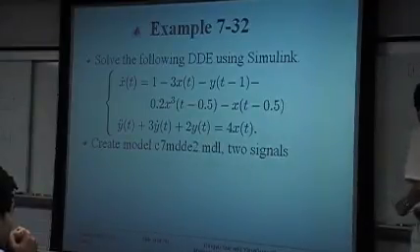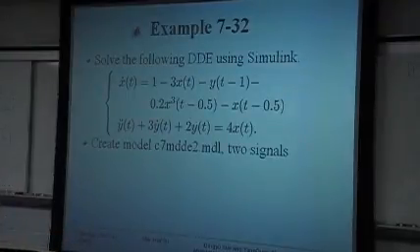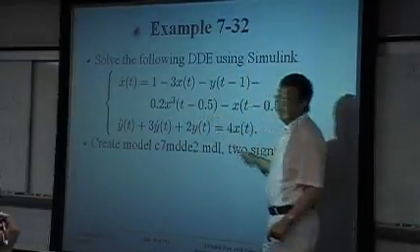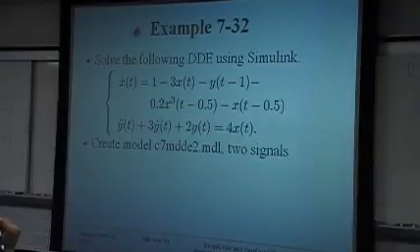Again, we have to use the block and then connect it like this. So what we should write here is 0.2 times u, we do not have to write 1 there, u cubed minus u. These are the last two terms. We assume that u equals this signal, so we can easily fill the information into that block.